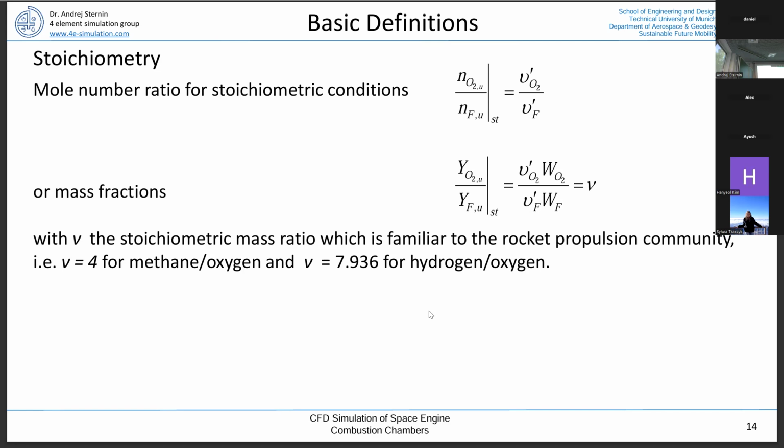So in terms of hydrogen oxygen, we in principle dilute the combustion process by adding hydrogen, lowering the temperature, but the effect of lowering the molecular mass of the exhaust is more efficient, and that raises the efficiency substantially. So that's an entirely different ballgame.